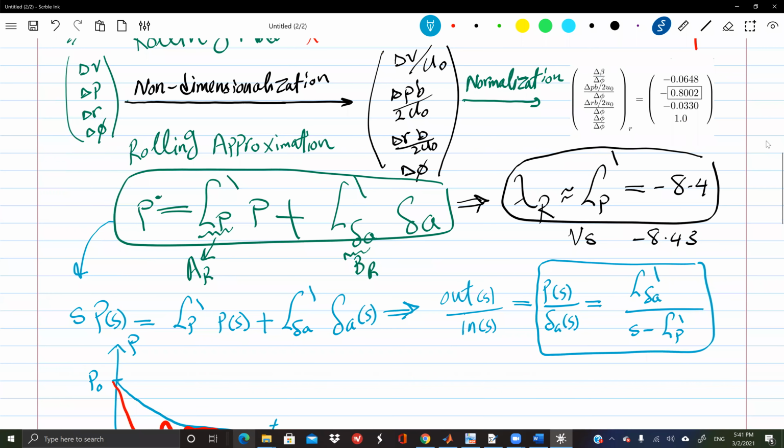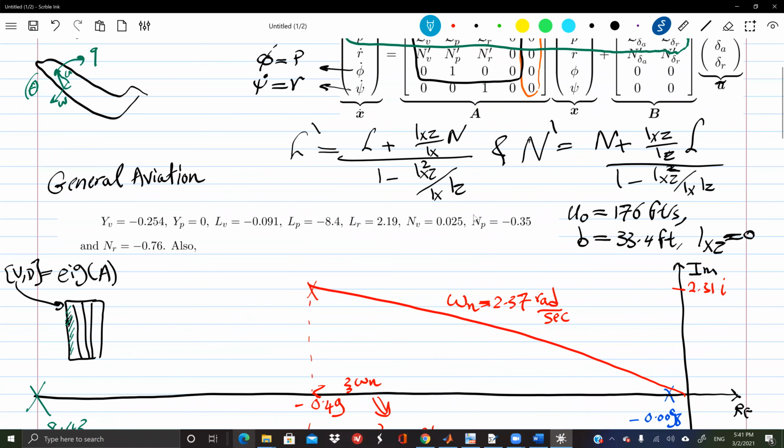In reality, is that coupling working in the same direction as the aerodynamic coupling or in the opposite direction? Not necessarily. We're going to talk a lot about the aerodynamic coupling today. Most of the lecture will be spent on it. There are several sources for aerodynamic coupling, but the inertial one is favorable in the sense that if you apply yaw to the right, you will get roll to the right also from this inertial coupling. But whether it's the dominant one or not really depends on the airplane.